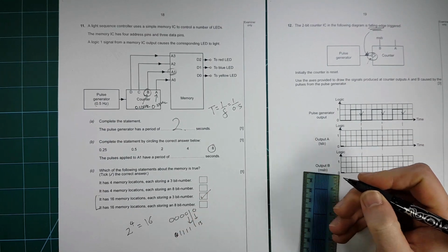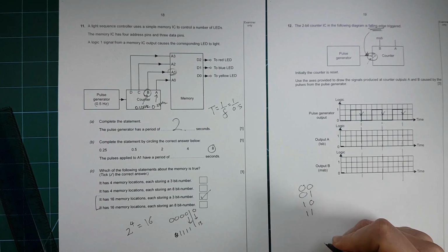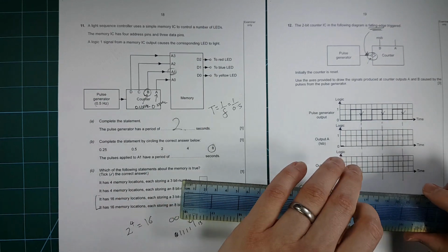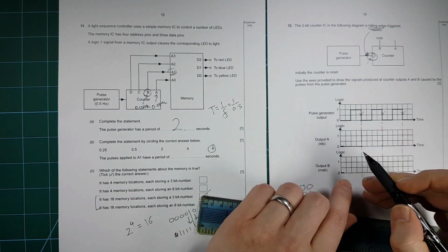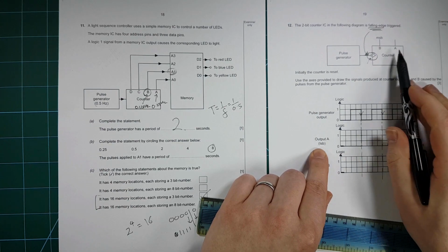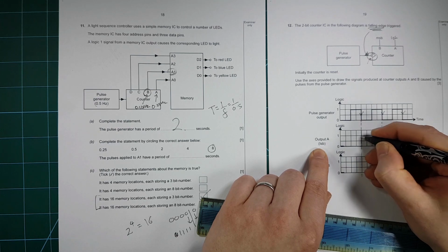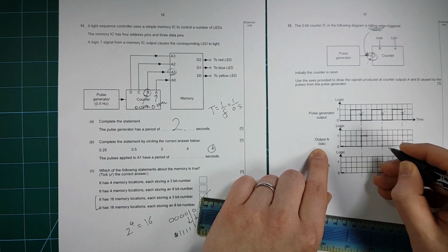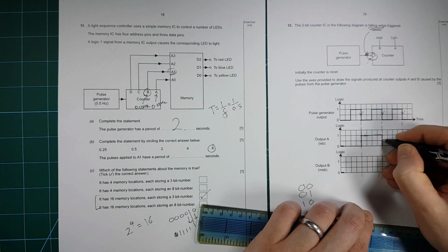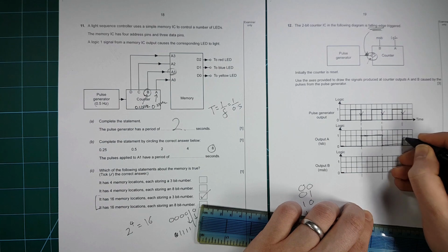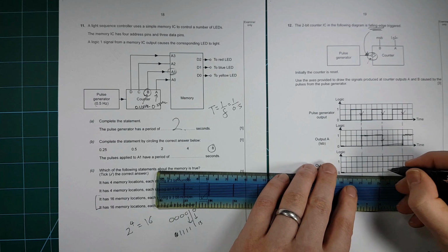Now the binary values that we're going to count are these, because it is a counter. At this falling edge here, the least significant bit is going to be A, so that's going to change at this falling edge here. The most significant bit won't change just yet. Then at this one, the least significant bit will change. Then at this one, the least significant bit will change here. And then on this falling edge here, the most significant bit will change.